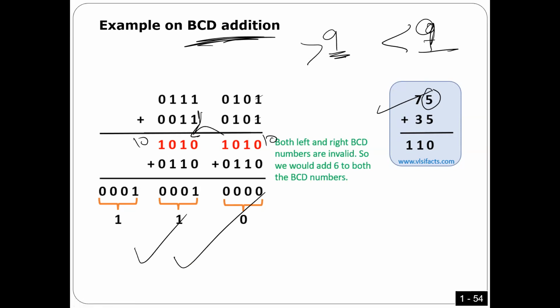Again, you got what I'm saying? So again, I'm going to represent every digit in 4 bits, and then I have to force this number to be between 0 and 9 because it's a decimal number. If you do the addition and you find the number is greater than 9, you have to do an adjustment, okay, to correct it, this way.